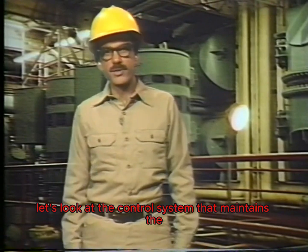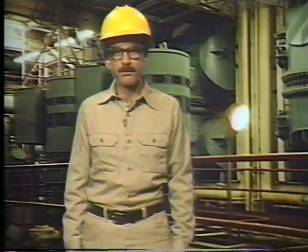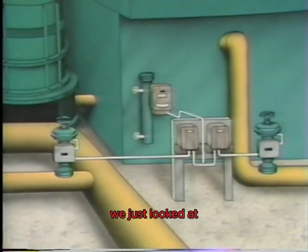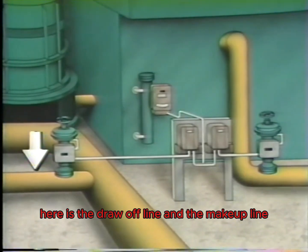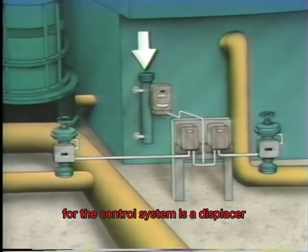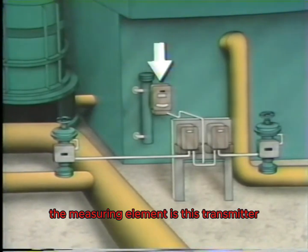Let's look at the control system that maintains the water level in the hot well automatically. This illustration is a close-up view of the system we just looked at. This part of the illustration represents the hot well. Here's the draw-off line and the makeup line. The primary element for the control system is a displacer. The measuring element is this transmitter.